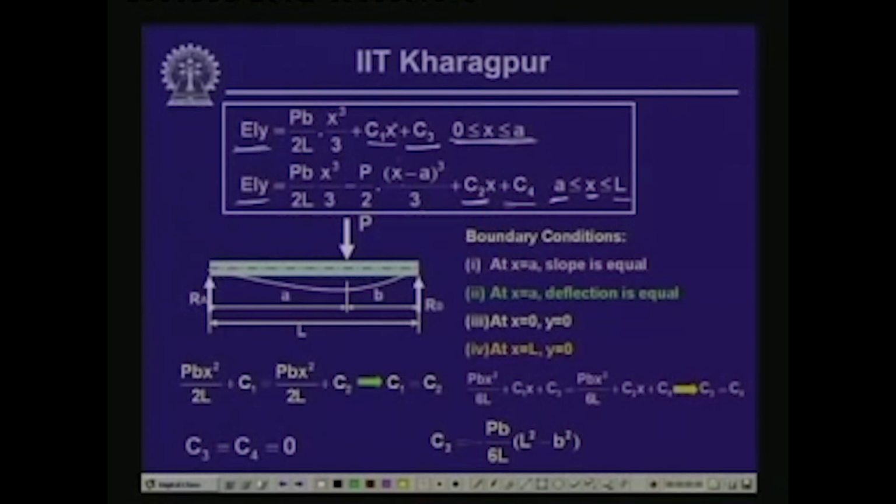Now, there are four constants C1, C3, C2, C4, and these four constants are to be evaluated from the given boundary conditions, or the support conditions of the beam and the loading condition of the beam. We will have to substitute the appropriate boundary conditions so that we can evaluate the values of C1, C2, C3, C4. As we have discussed in the previous lesson, we can have either the static boundary conditions or the kinematic boundary conditions, and if we impose them, we can evaluate the unknown constants.